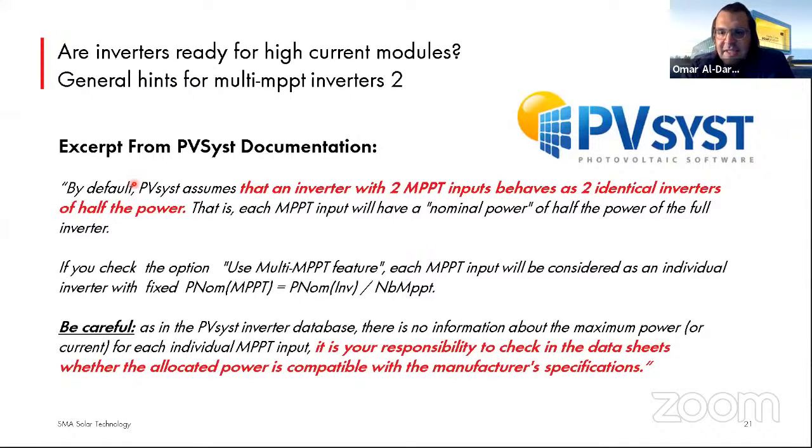A final note on PVsyst. Not a lot of people know that, but PVsyst actually models a multi-MPPT inverter as a number of separate inverters. So let's say you have a 50 kilowatt inverter with 5 MPPTs. PVsyst would model it as 5 separate 10 kilowatt inverters, which is entirely not true. That does not really reflect the real conditions at site and how the inverter behaves.